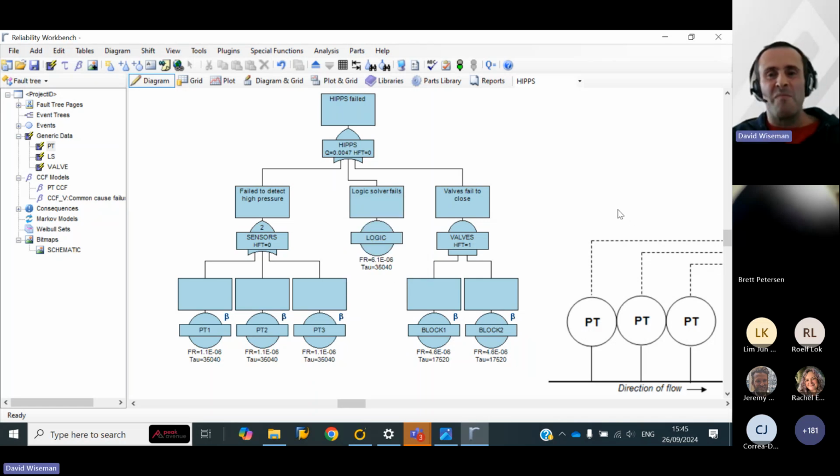So a couple of numbers I'll point out here. I'm going to go into the results proper in a moment. I'll point out here, you've got unavailability, or in the parlance of functional safety, the probability of failure on demand. So that's your PFD. What's the probability that if you ask this safety system to work, it doesn't? What's the probability that when you make a demand on this system, it is not going to work? That's coming out at about 0.0047 based on the numerical data we entered at the bottom.